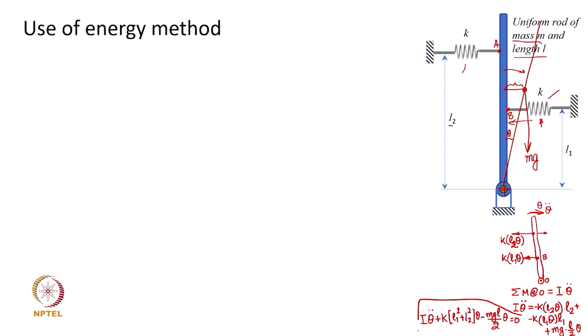So, this actually is now my governing equation of motion. Here the gravity is accounted for, because the rod is assumed vertical. If it is assumed horizontal, so that the bar swings in the horizontal plane, then the gravity will not play any role in the moments generated trying to restore the original equilibrium position.